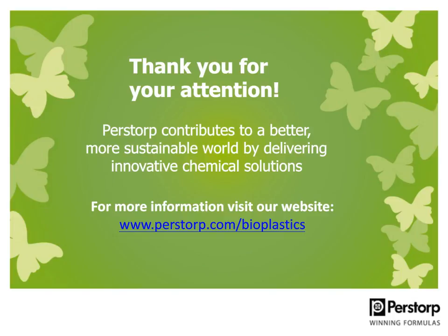I can add that based on the melting point and the structure of PCL, that is a benefit when it comes to biodegradation. It starts enzymatically, and the microorganisms really like to chew on Capa, and that's how the biodegradation process is initiated, followed by hydrolytical degradation. So that's also why the product is so stable in use.